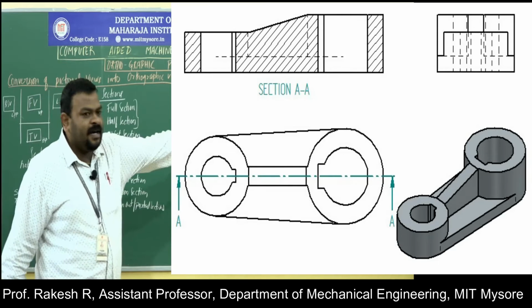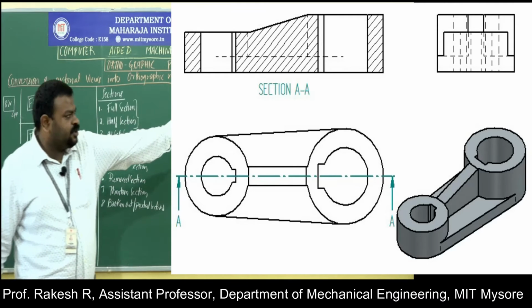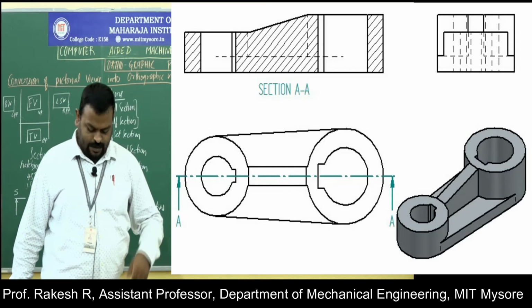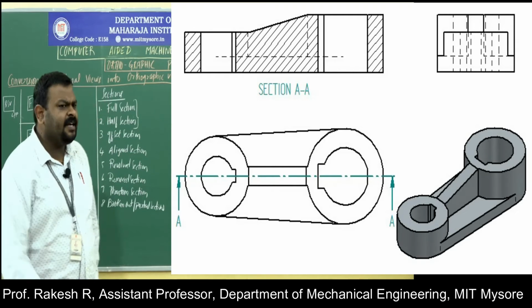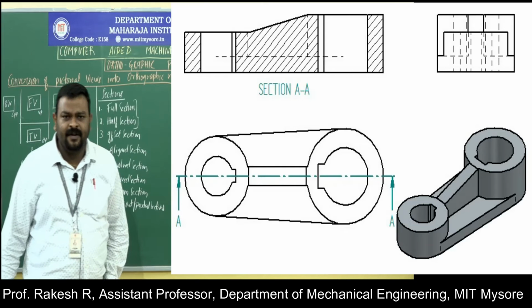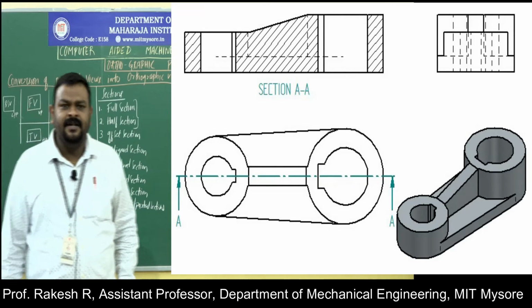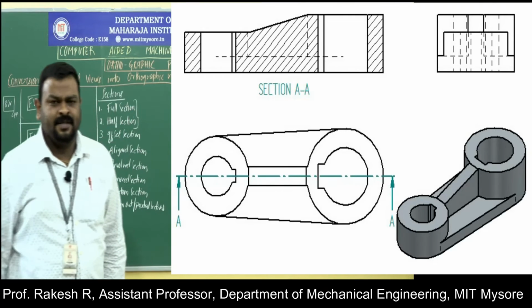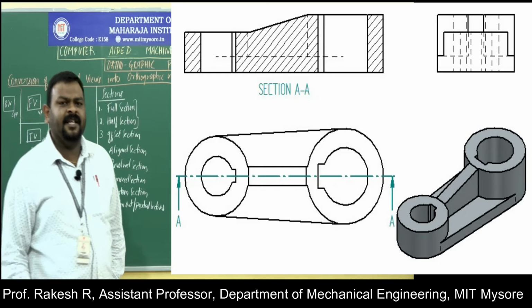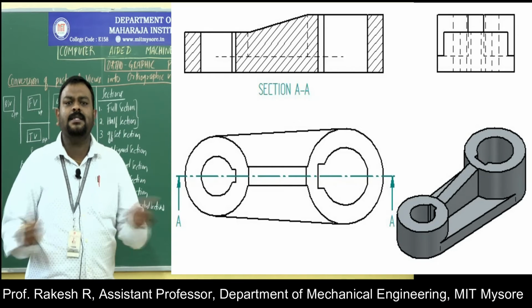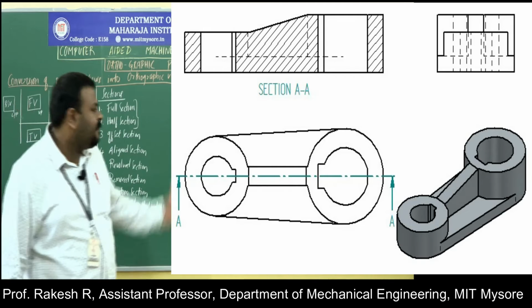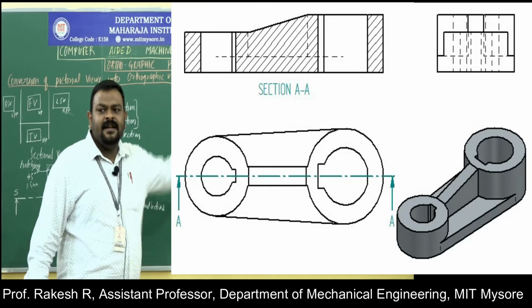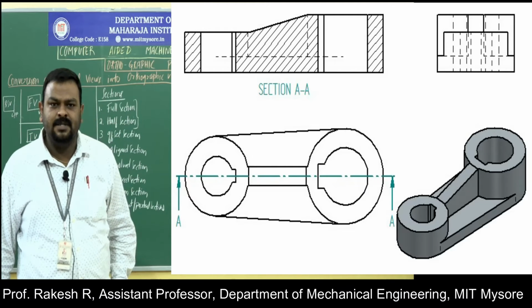So this part will be 3D. This is showing the three different views: front view, top view and side view. If I write the front view, top view and side view for that, it will remain constant. It is the same as the previous case. In orthogonal projection, the first thing we need to identify is the maximum portion of the drawing. That maximum portion will be written on the front view and then the other two views will be written based on that.